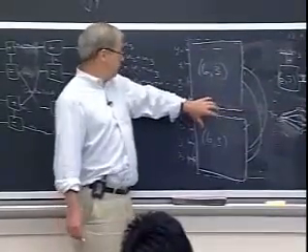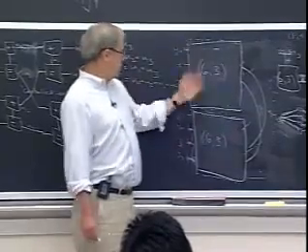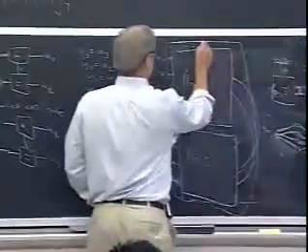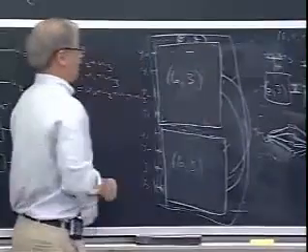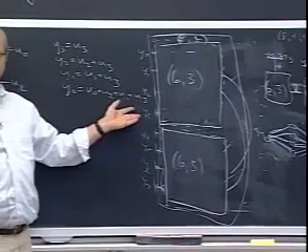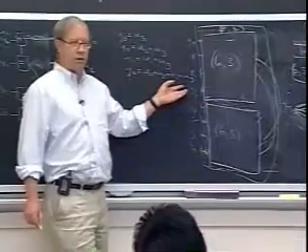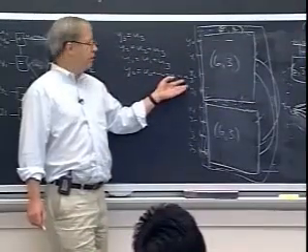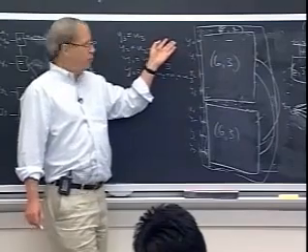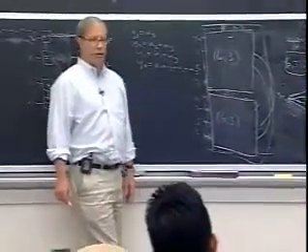And we're going to want a decoding algorithm for a part of a system, say this 6-3 part, or say something else, say this whole thing is a part of the system that's just 8-4. That yields soft probabilistic information in the output that we can then feed into decoding algorithms for other parts of the system. So we won't want to make hard decisions. We'll want to feed the whole vector of a posteriori probabilities from one partially decoded part of the system into some other part and then go decode that.